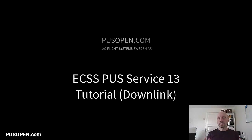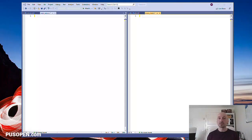In this video I will tell you what ECSS PUS Service 13 is and how to use it in the PUSopen framework. PUS Service 13, or PUS 13 as we call it, is used to uplink and downlink large data. So let's say that the sender, your payload computer, wants to send processed image data to the ground station.